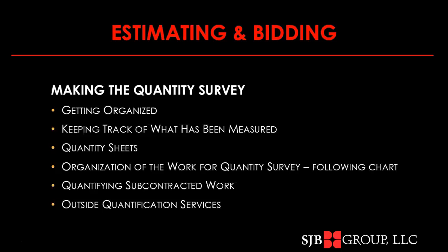The items to be considered for consistency include: identify the source of each entry by its drawing, plan sheet, section of the specs, etc. Learn and use standard abbreviations in your descriptions. List the number of items and dimensions in the same order for every entry.